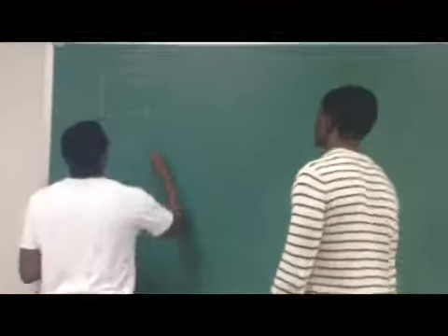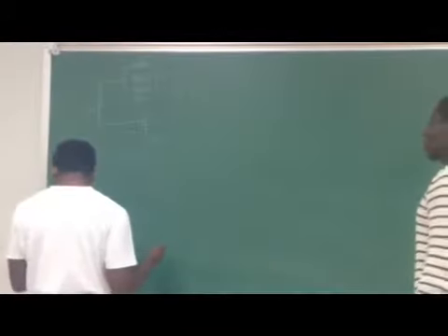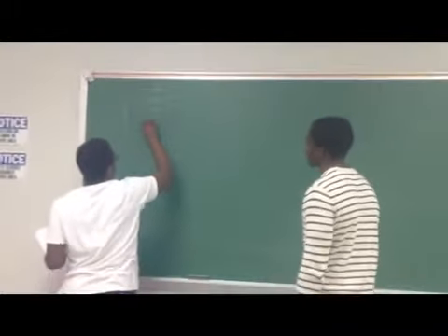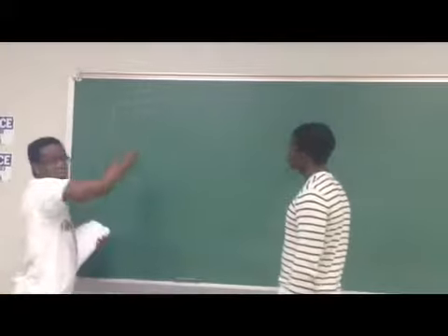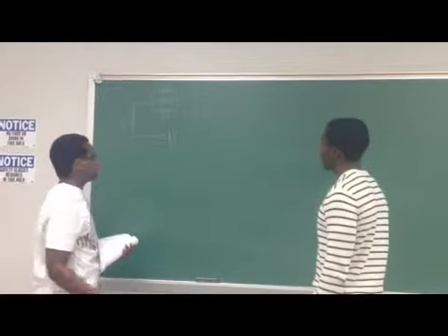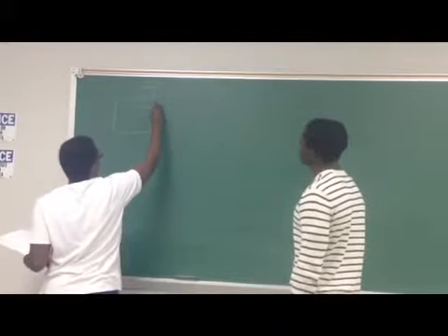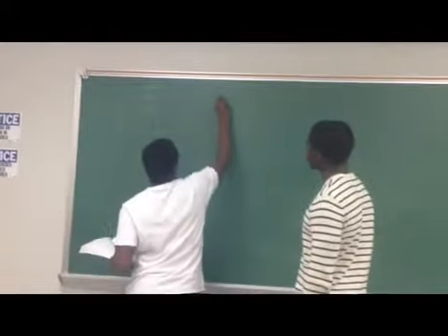So one thing we know is that since this is 12 by Kirchhoff's voltage law, and since this section of resistors is a parallel circuit, we know that the voltage across each resistor is 12. Because this voltage on the whole has to equal 12, and it's a parallel circuit, so the voltage remains constant.